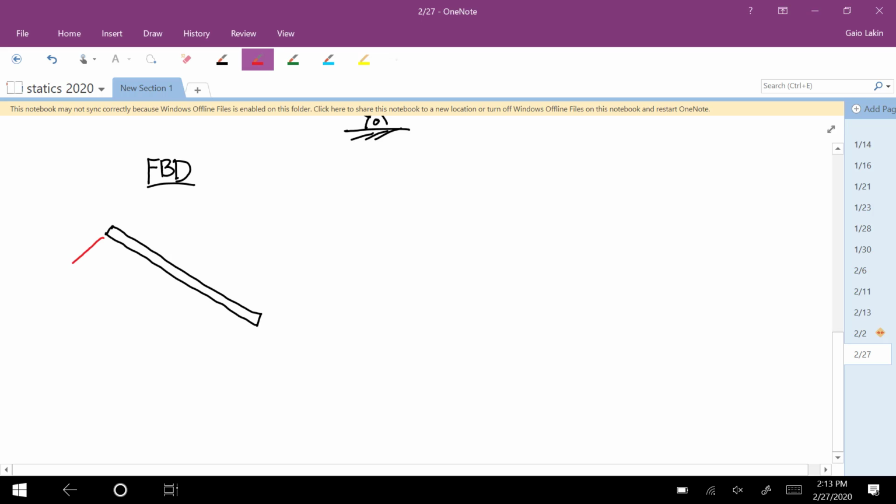There's a force up here. I'll call that N. There's a weight force of 20 times 9.81, so 196.2. A 500 Newton force at the center, and then the pin joint down here, there's a full unknown force vector, I'll call that R. And that's all the loads. And I'm going to use this as the about point.